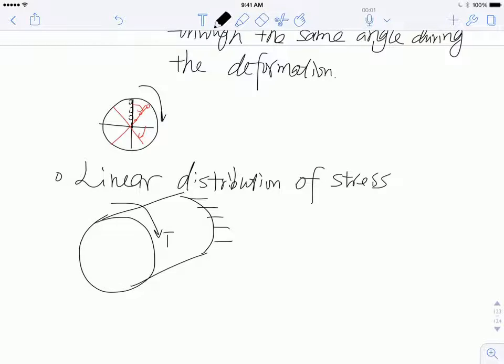Imagine this is a screw, but it's bonded to the surface of the wall, and I use a wrench trying to turn it. Now, if I want to turn it, there's a special point right in the rotational center. It has a very small amount of stress, which I'll show you later. Right, so the stress being applied, tau, is nothing but T times C divided by J.